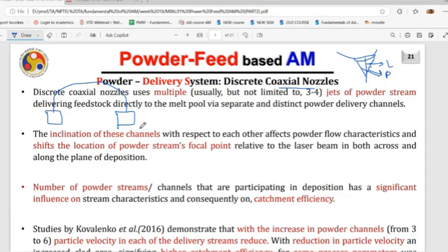There is also another significance of why we use a distribution instead of one powder particle size, which I'll talk about. This distribution is very important because the powder is coming through the nozzle using a carrier gas. Here argon is the carrier gas that we use. As it's inert and has some weight, it can carry the powder from the powder feeder to the deposition zone.